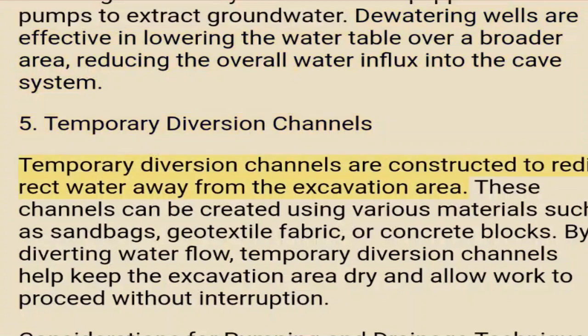5. Temporary diversion channels. Temporary diversion channels are constructed to redirect water away from the excavation area. These channels can be created using various materials such as sandbags, geotextile fabric, or concrete blocks. By diverting water flow, temporary diversion channels help keep the excavation area dry and allow work to proceed without interruption.